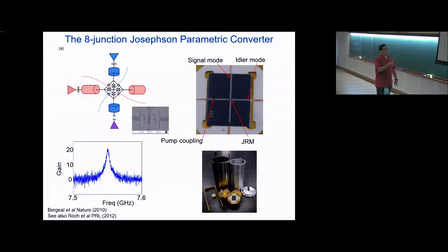This is a silicon wafer. Here you see the lambda over 2 ports. Here are the physical microwave connections going out of the box to some SMA connectors. And again, here you can see the very big gap here that makes it a very small capacitor for the pump port. There are 2 other gaps here. They're just a few microns. You can't see them with the naked eye.